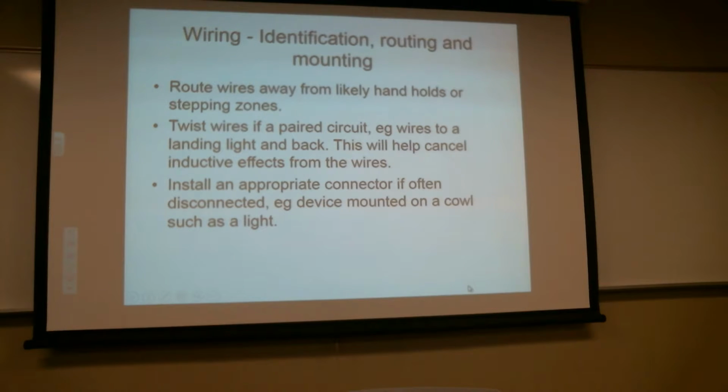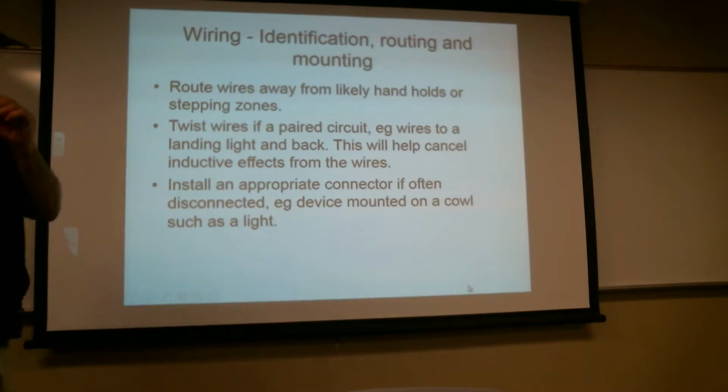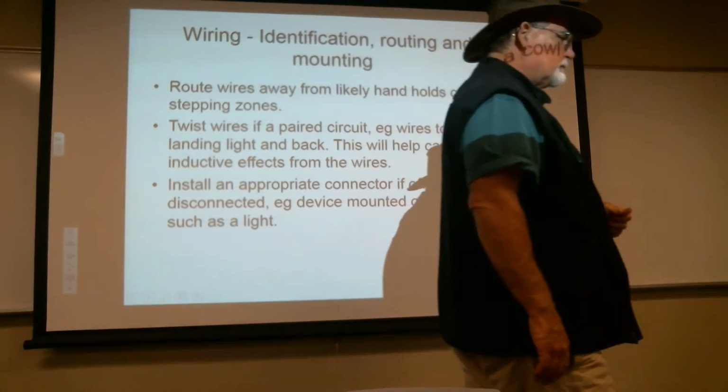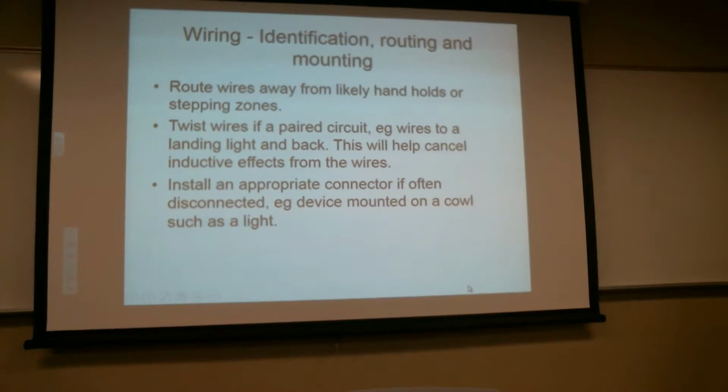You definitely don't want to route a wiring harness so that it looks like a very convenient step or handhold. And that's also true even if it's in a conduit. You do not want the conduit to be regularly stepped on, swung from, cargo attached to, and dangled from, that kind of thing.